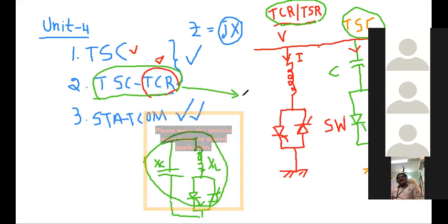And once you change the input speed, that is input power, mechanical power, the speed won't change, the frequency won't change, because it is fixed and decided by the infinite bus bar. Then what will happen? Real and reactive power flow will change once you change the excitation or the mechanical input to the generator, that is the field rheostat of the motor, which is the input you are changing. So real power and reactive power change once it is synchronized to the infinite bus bar.